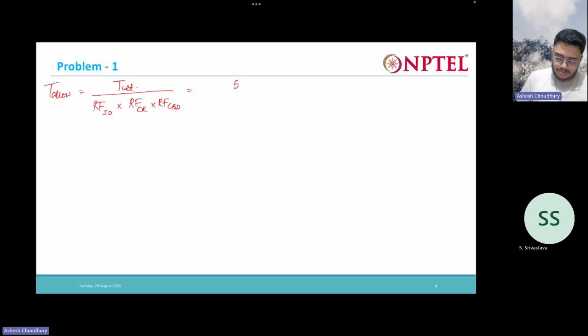So I will just use the basic values. So this one will be 1.2 times 2.5 times 1.2, which gives us the reduced value. The ultimate tensile strength is 50 kilonewton per meter, but we have used some reduction factors to reduce it to 13.2 kilonewton per meter. Okay.